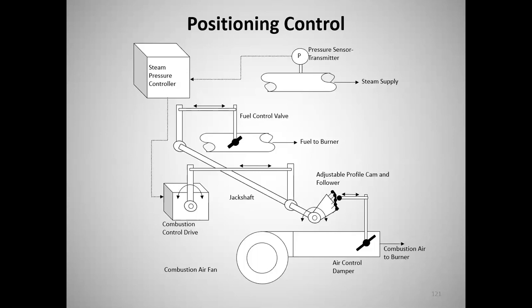Well, that's going to affect your tuning on the boiler, your air-fuel ratio, okay? So if you have a system like this and you tune it during cold weather, then you're probably going to get a little bit less air because the air is denser. Then all of a sudden it warms up outside. And if you don't retune it, then you're not going to have enough molecules because it's going to be trying to blow the same CFM at a given firing rate.